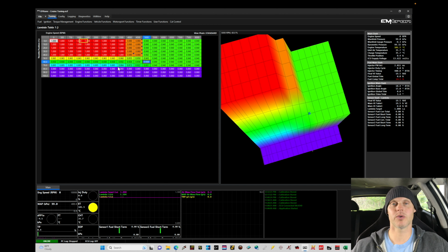The first thing I want to jump into here in this training module is going to be setting up our O2 transport delay table. Now in that last training tutorial, I went through the entire part throttle tuning process. We worked with the closed loop correction. We were fine, everything was working correctly. The short-term adjustment was doing exactly what it should.